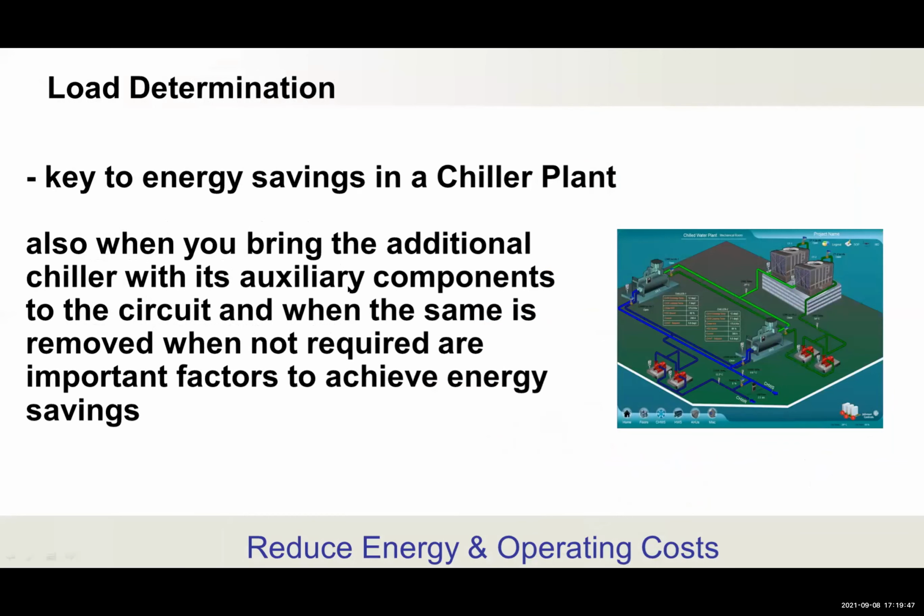So when we have, for example, 5 to 10 chillers in a building, on a ground reality basis, we are not supposed to work any chiller for any number of hours more than what is required to operate. That is where the energy bill is going to get the hit. So it's very important that a chiller plant management system is installed properly and operated, and the load determination takes care.